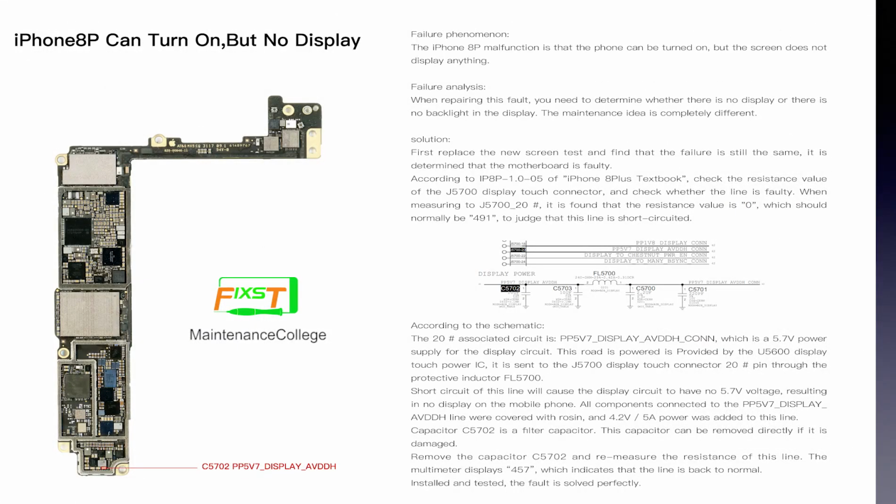This is the iPhone 8 Plus. The phone can turn on but has no display. When we repair this problem, we need to determine whether there is no display or no backlight in the display, because for different problems the repair idea is different. First of all, when we meet touch, display and other problems like this, we first need to change a new LCD to test it.